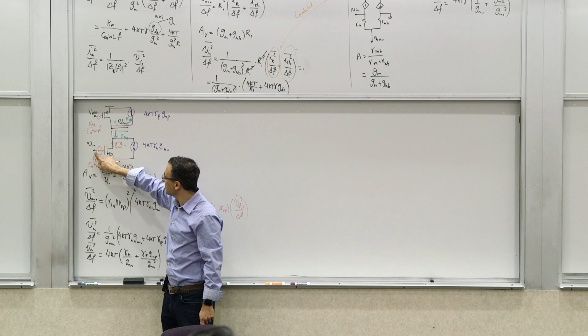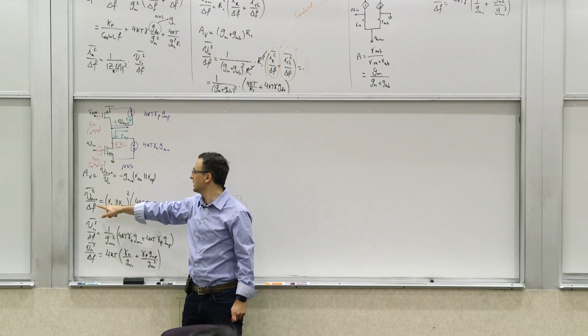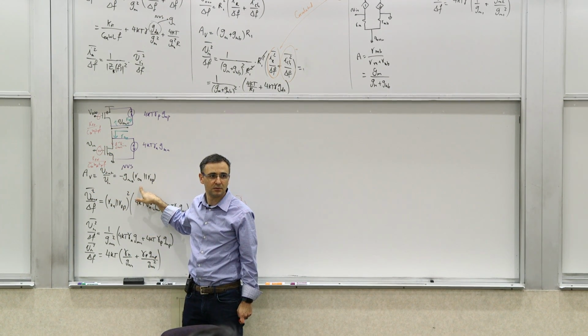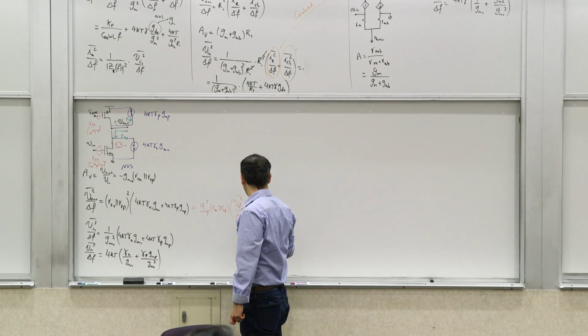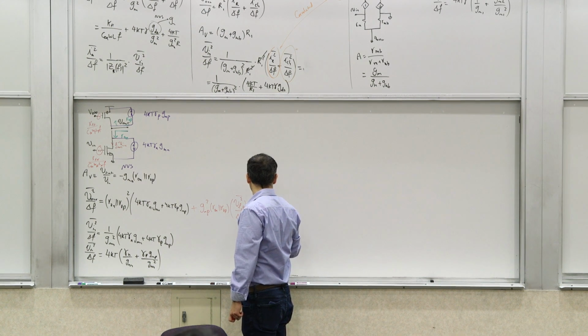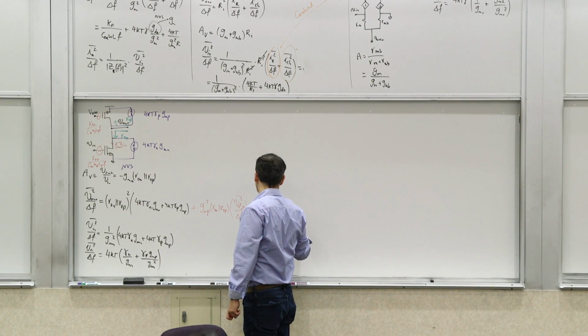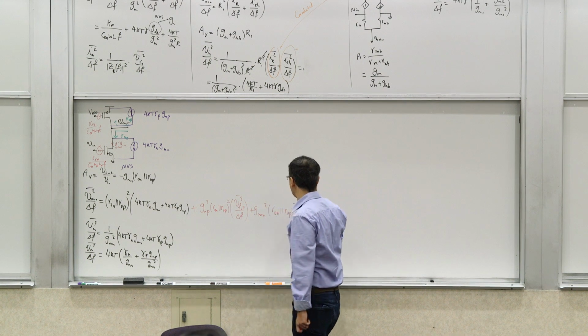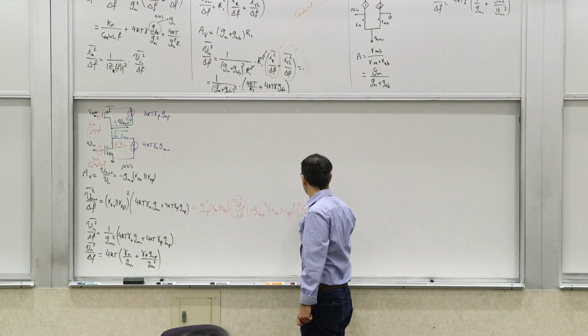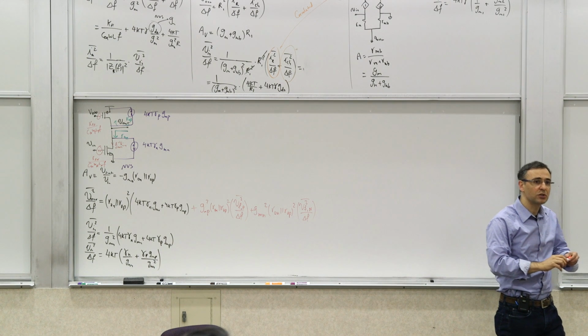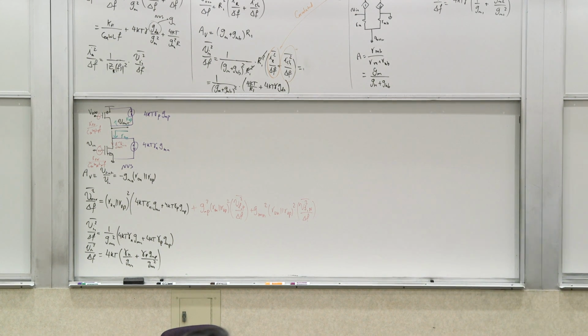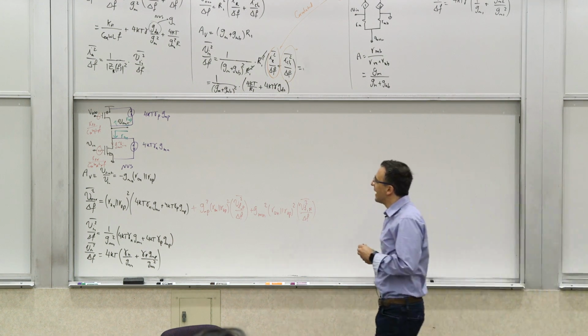Now, the transfer function from this voltage to that voltage is just basically the gain that we have already calculated, right? Because it's the same terminal. So that one would be amplified by GMN magnitude squared, RON parallel ROP, and this should be squared too. VFN magnitude squared over delta F, so the power of that. So now these two new terms are due to flicker noise. Does it make sense? So now we have these two additional terms.